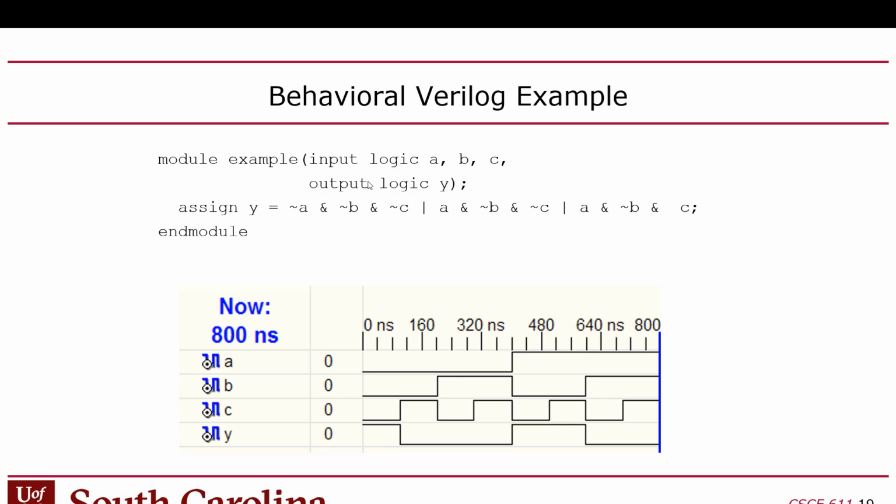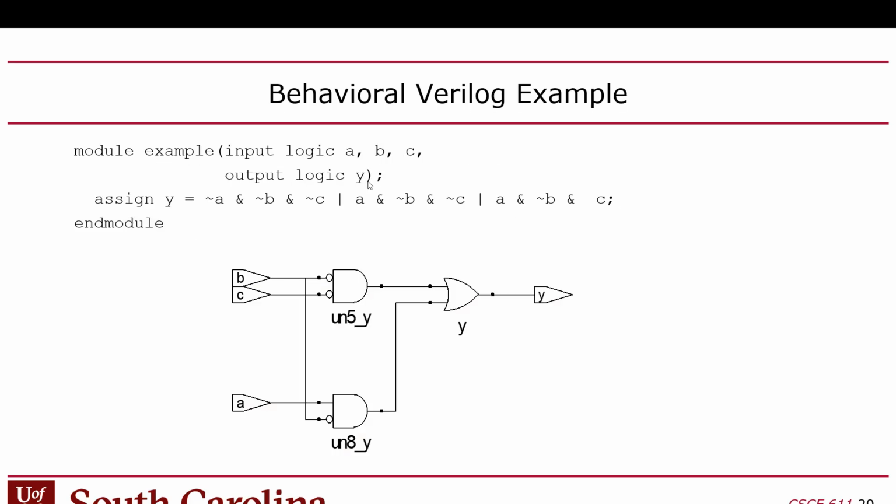Although we've been thinking about introducing that timing analysis. I'd like to do that. That's something I've always wanted to do in this class, other than just say, oh, run it at 50 megahertz, because I think you could probably get these RISC-V CPUs to run at 200, 300 megahertz, but it would take some iterating on the timing, right? And then you have to understand how to use the timing tools. In this class, though, we focus just on the behavioral design, right? Just getting the behavior, not necessarily, we don't focus too much on the deployment, the physical.